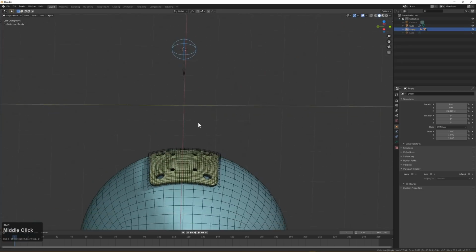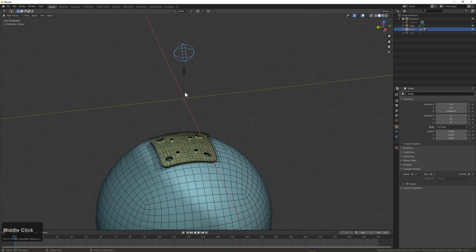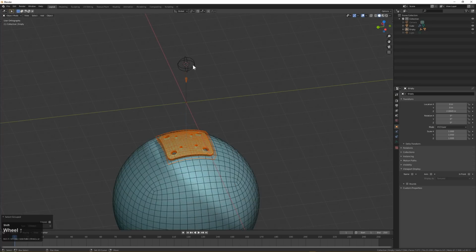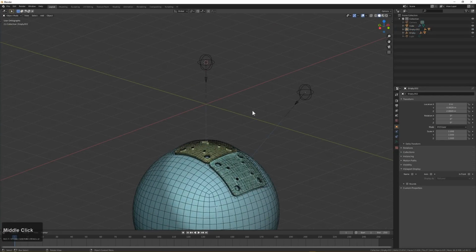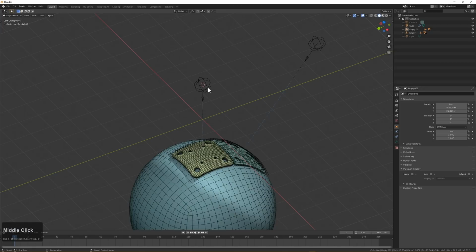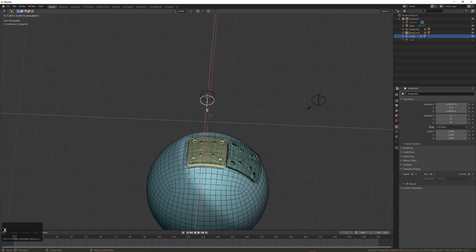Select this, and let's say I wanted to duplicate this and get a little more experimental with it. I could press Shift G, which selects group and brings up this handy little menu, also available in edit mode with very different options. We'll select children. It'll deselect everything and select children. So we'll need to select the main object, and we'll duplicate it one more time and move it over so we can isolate which empty that is. And we'll place that variant of the plate. To show that one more time, I'll press Shift G, select this, children, and we'll duplicate this